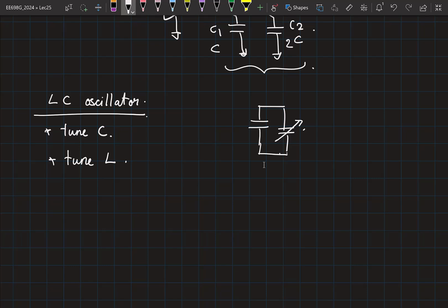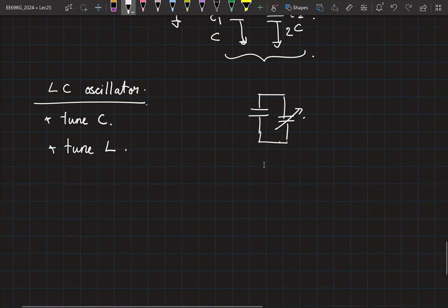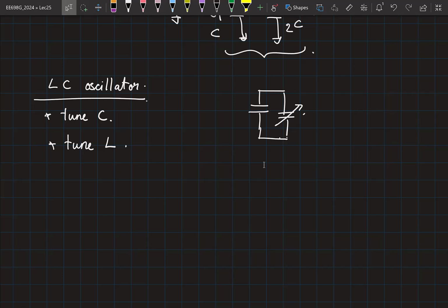Have you seen an inductor layout? You have seen chip layouts, right? If there is an inductor, you'll be able to make it out because it's going to take up a lot of area. If there is a transistor, you will not be able to make out an individual transistor from a distance if I were to show you a picture. But inductors are huge. So putting in more inductors means you're losing more area.